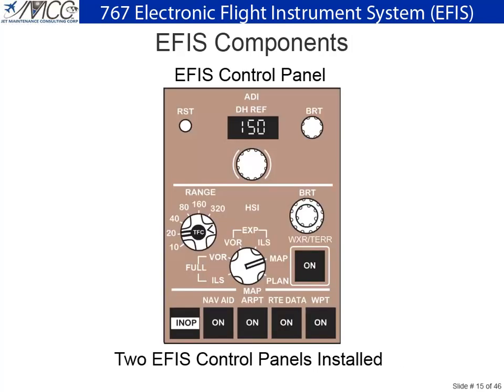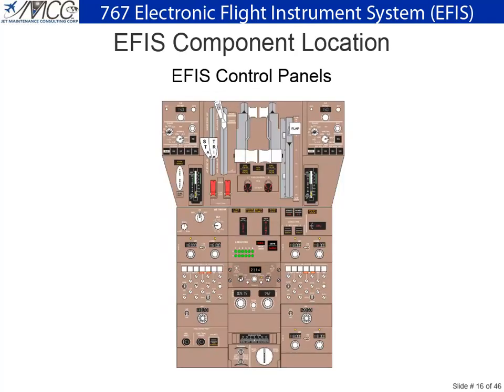There are two EFIS control panels. The upper portion of the panel controls the EADI, while the lower portion of the panel controls the EHSI. The EFIS control panels are located on either side of the aisle stand.